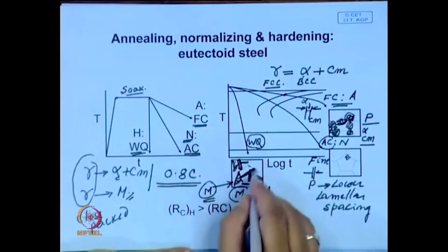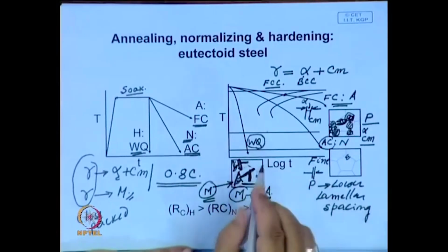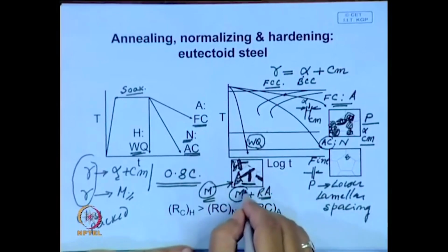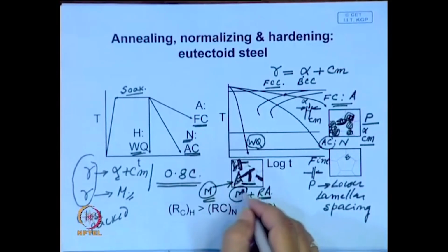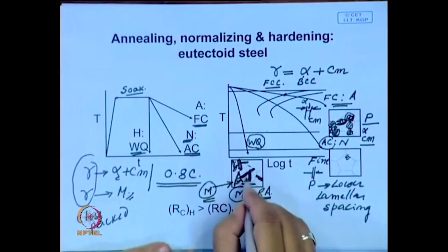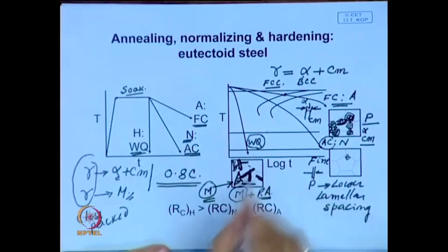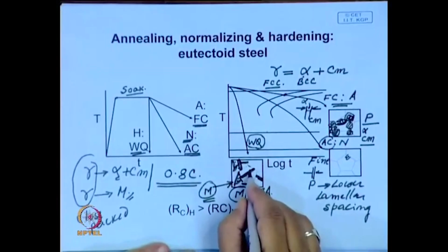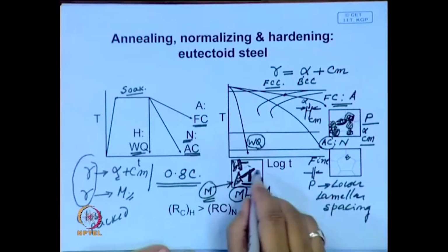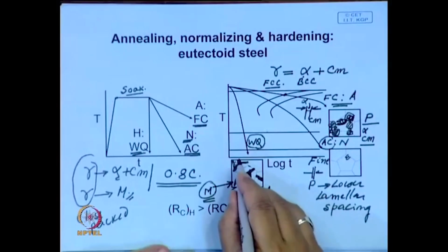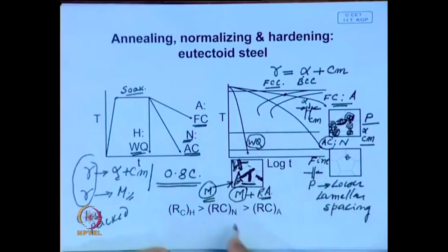The structure will be so fine that it may not be resolvable. In fact, under an optical microscope these martensites are very bright, and they often do not etch well, although the boundaries may show. But if you temper it slightly, as we will see, they etch very well and you can see this structure even under an optical microscope, but not the final details within one plate of martensite, because there the level of resolution needed is in the nanometer region, which is extremely small. So, you need an electron microscope to resolve the structure within the martensite plates.